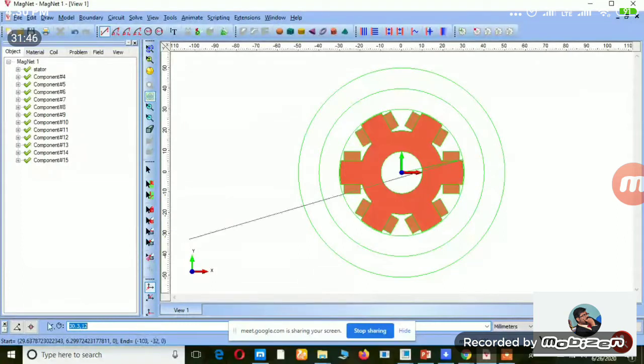So what I want to do, at the bottom there is the option r comma theta, and this r comma theta has to be changed into del r comma theta. For that, I go for the toggle option. Again, the del r comma theta is now available. So this point is now considered as the starting point. Now I want to draw a line parallel to the x-axis. Parallel means there is no need of angle. The angle is 0. The line is going to be drawn in the forward direction, so there is no need of giving negative here. So just give enter here.